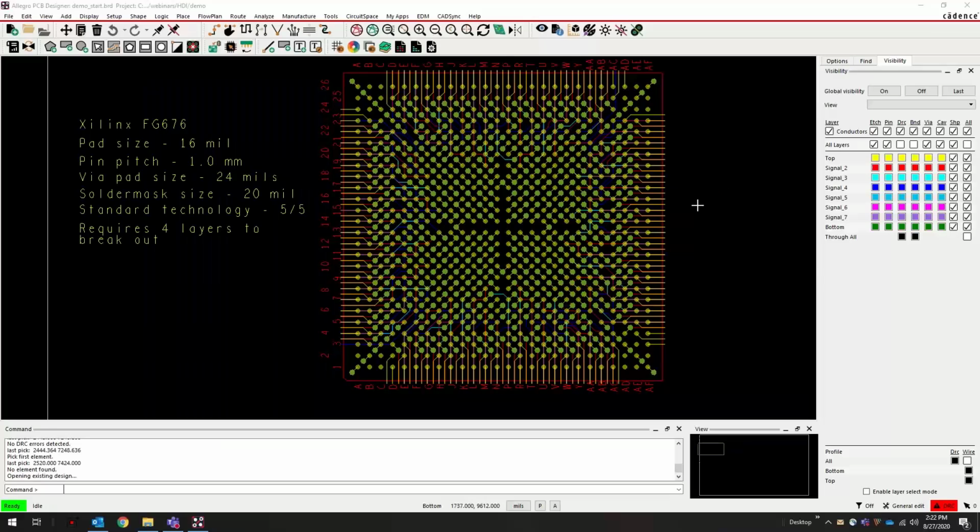Okay, thank you, Brianna. So what I'm showing you today is in Allegro PCB Editor with the miniaturization option. This option allows you to actually use microvias in your design and constrain them as a separate element in the board database. And what I'm showing here is a 1 millimeter pitch BGA that I've routed out according to how Xilinx has recommended fanning it out.